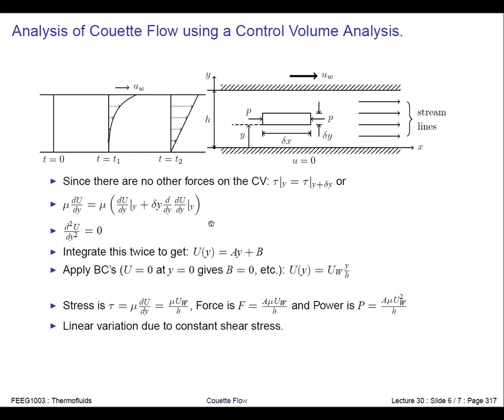Okay, and let's think about why this is. So we said that there's a stress balance in the fluid, and there are no other forces. So effectively, what's got to happen is the shear stress in the fluid is going to be constant, because effectively the fluid wants to spread the load out, and it spreads the load out by enforcing a linear velocity profile. Because if we take this equation and we differentiate it to work out du by dy, we can work out what the shear stress is and the force. So this is the force that you have to apply to the plate.